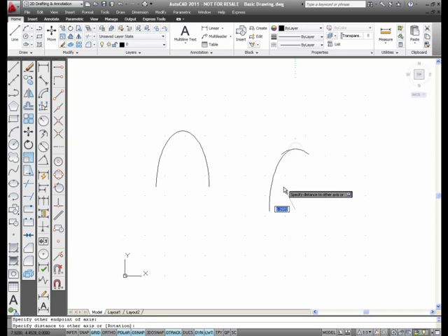Once again, but this time I'm going to start my ellipse arc on the left side. I'm drawing it underneath. So if I start on the right, counterclockwise, this is the arc I get. If I started it on the left, I'm sorry, I'm getting my counterclockwise and my clockwise mixed up. If I pick it here, go counterclockwise, I end up getting below. Pick here, go counterclockwise, I end up above.